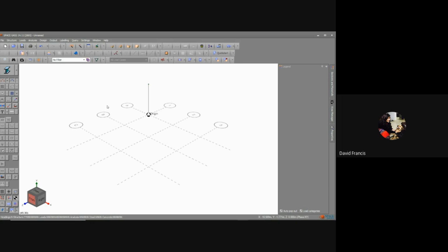It's basically physically flat, and there are no round corners. So particularly if you're wanting to make some changes to a part of the model, orthographic is quite useful. One thing to remember is that if you leave orthographic turned on and you have a large model, you'll find things going slowly. Your graphics is trying to rotate an orthographic view. So remember to always right-click and come back to perspective view.